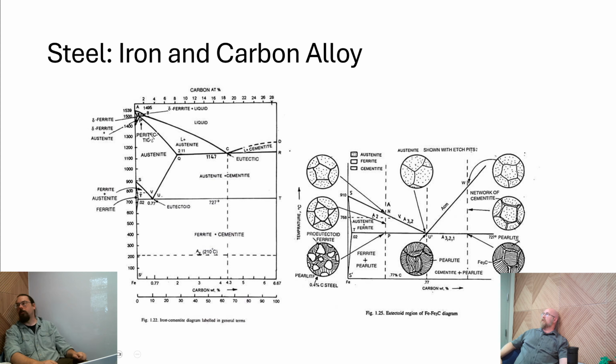There's a lot of things that we like to do here from a material properties perspective. We're forming different alloys, which becomes important. If you think about it, in order to form these alloys in the first place, we have to melt it, and so it's really just about controlling the mixtures and how it cools, and at what rate it cools. If we cooled it down fast from that high a temperature, we're going to get different phases than if we cooled it from the same temperature range gradually and let it go through this eutectoid region. Exactly, because we get different things if we freeze it at that high-temperature phase.